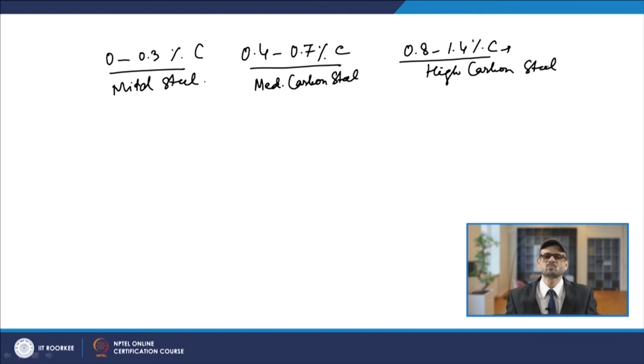And if you need ductility, white cast iron cannot otherwise be used, but when you malleabilize it, when you give it the annealing treatment, then you can use it for automobile components, because it develops good ductility and malleability. And SG iron, which is found only in the cast form, has a good combination of strength as well as ductility.